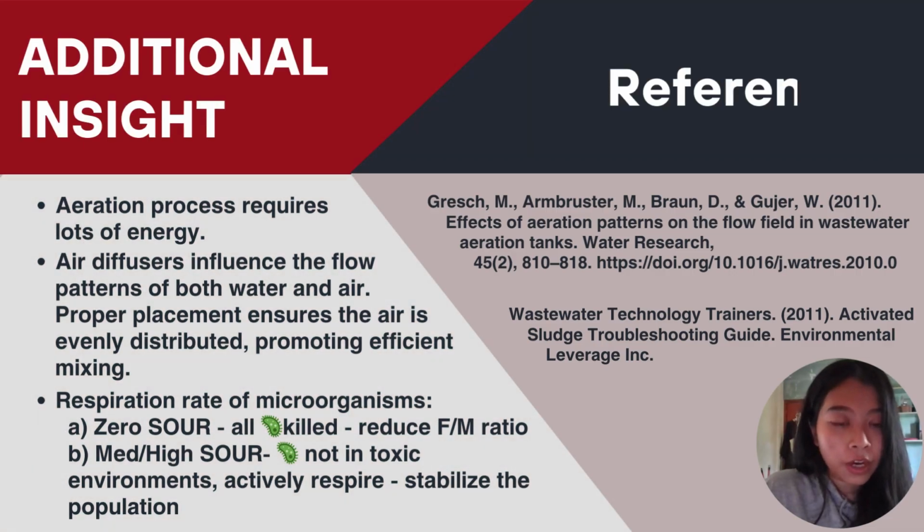In the aeration tank, there are several parameters that need to be taken note of. First of all, the aeration process requires lots of energy. Aeration process refers to the oxygen supply for the microorganisms in the tank. Next, the air diffuser placement is really important in the aeration tank. It influences the flow patterns of both water and air. Proper placement ensures that the air is evenly distributed, promoting efficient mixing between the water and the air. Last but not least,